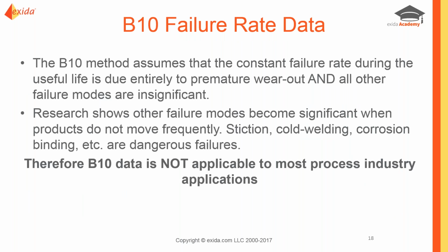The B10 failure rate data does assume wear out. All the failures are due to premature wear out, and it does not consider infrequent modes of failure. In the chemical process industry, the devices are not moving. The demands are low, so our valves may sit for some period of time before they are asked to move.